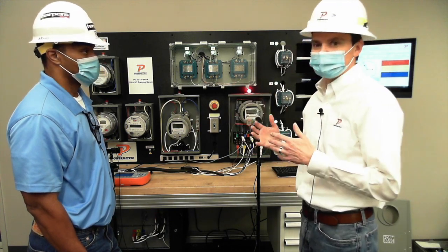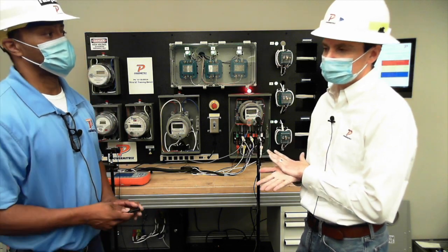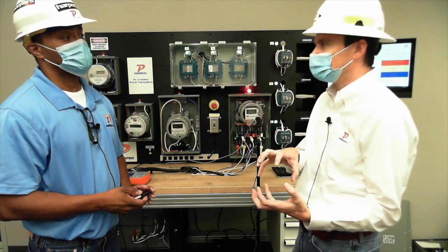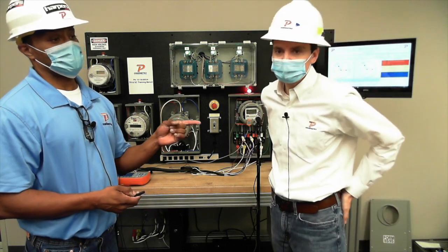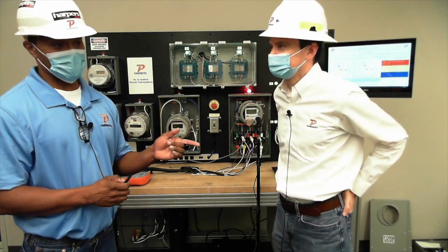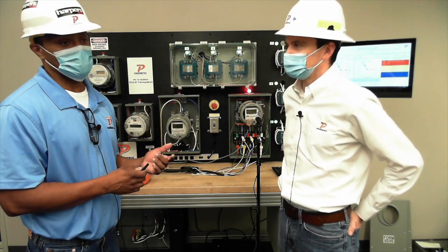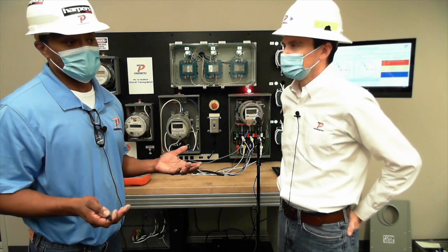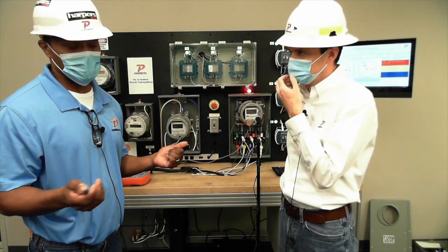So from a demand point of view, I think it's not a bad thing to use a load box test in this case because you can simplify your actual test. And also, it's a good thing too, let's say you get there and you're looking at the current and it's going up and down, up and down. So if there's an inconsistency in your current, hey, why not run a phantom load on it and get some consistency and go from there.